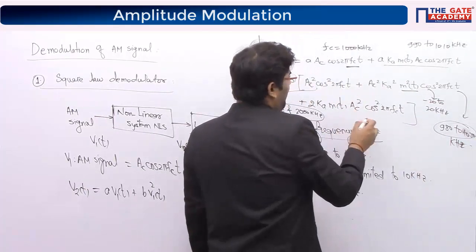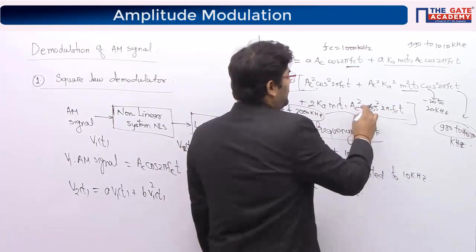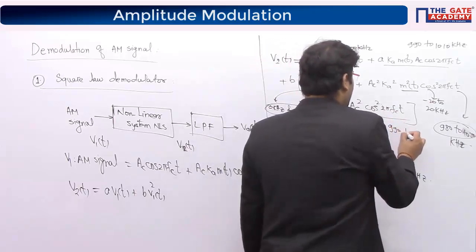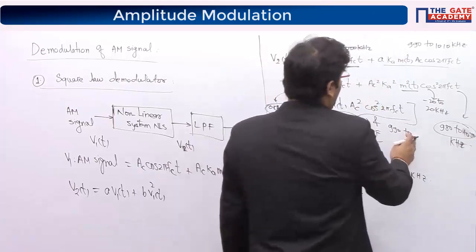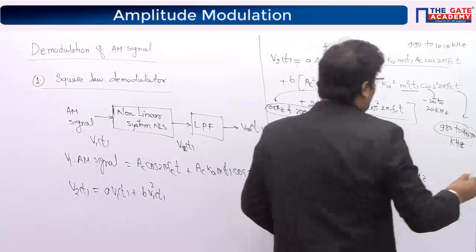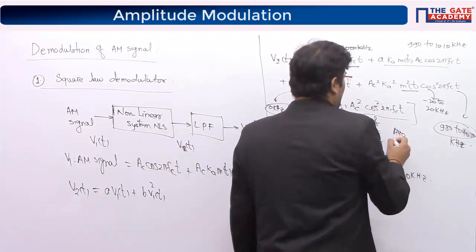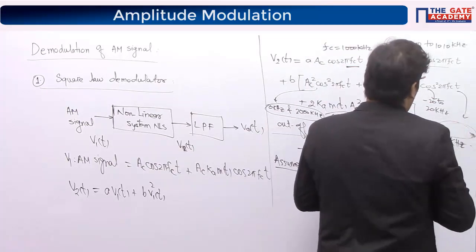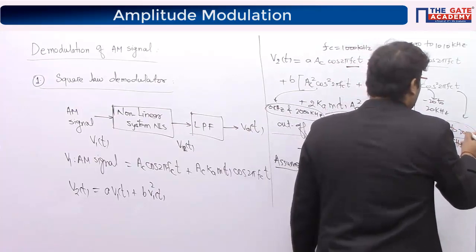This is the signal which we are looking for. It will also be written as 1 plus cos 4 pi fc t. So it will give you minus 10 to 10 and, not 980, sorry, because it will be cos 4 pi, it will be 2000 minus, so it will be 1990 to 2010. And similarly, since it will be cos 4 pi, it will be 1980 to 2020. Please change it, guys, to 2020.